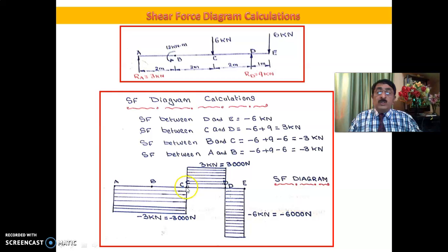What you have to do, and you have to show at least in this way in the exam: clearly show the calculations and draw the shear force diagram using pencil and scale. Make it as neat as possible. At least give this finish. Whatever we have got now has to be verified using Ansys later on. Now the shear force diagram is over.